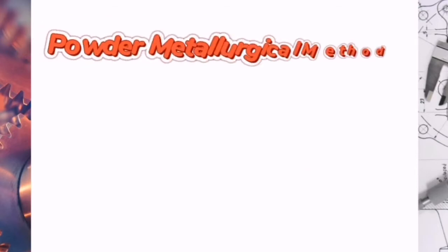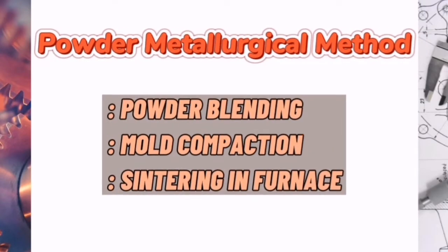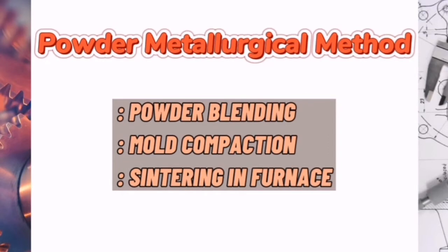In the other method, the alloy is produced via powder metallurgical methods. In this process, a mixture of pure nickel and titanium powders, which is the pre-alloy, is pressed and heated to low temperatures, lower than the melting point of the batch. In addition, the development of the intermetallic process, which is normally exothermic, raises the system temperature and triggers the occurrence of eutectic and peritectic processes and melting of the batch, which increases the system homogenization.